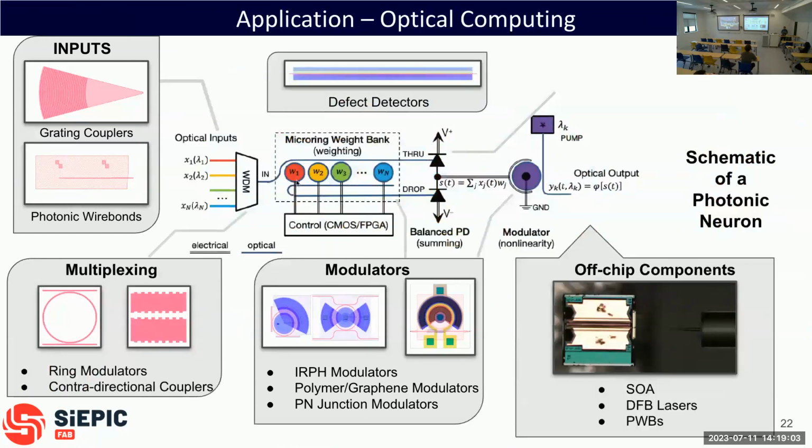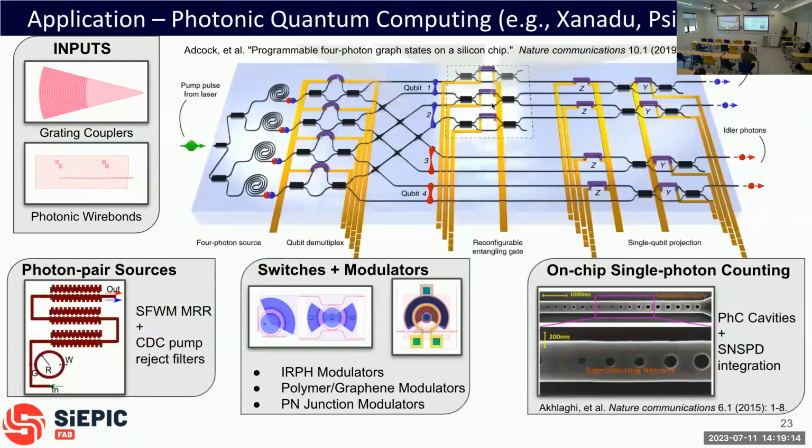Of course, there's a little bit more to it than that because you have to include the energy cost associated with the lasers, the detectors, the electronics. You have to pump through tens of gigabits per second of data. But once it's in the optical domain, especially when it's flowing through its passive linear matrix, that stuff is all for free. And it turns out that the scaling behavior actually works quite well. You actually get crossings for free in optics, whereas in electronics, you have to go over to avoid capacitance, but optical beams don't interact. So you can have light just cross straight through each other and build these linear networks.